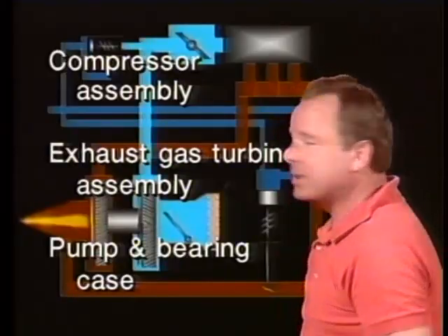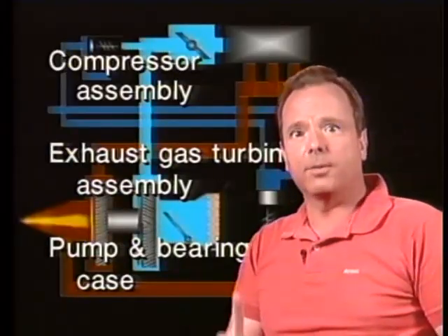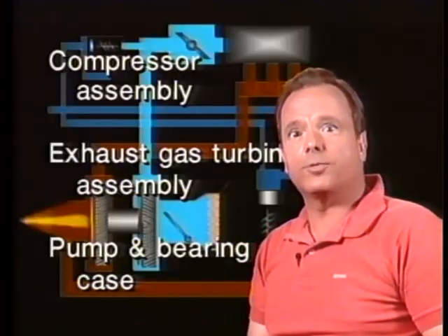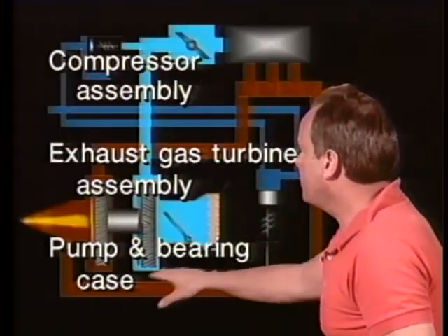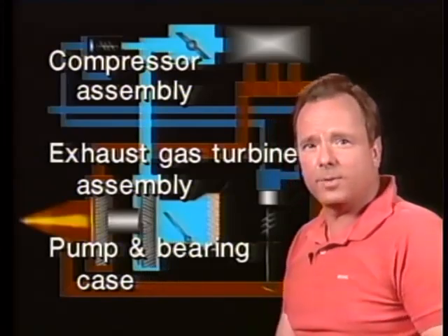What are the three parts that are typical of a supercharger for a large reciprocating engine? It's the compressor assembly, the exhaust gas turbine assembly, and the pump and bearing case, the case that goes around the whole thing.